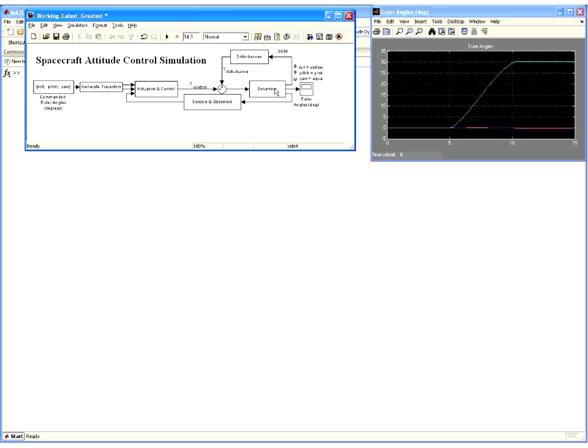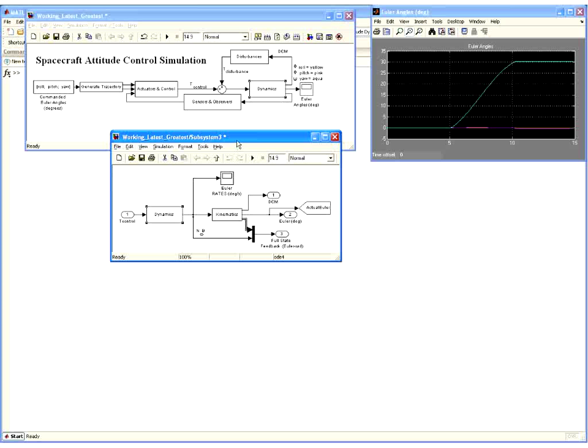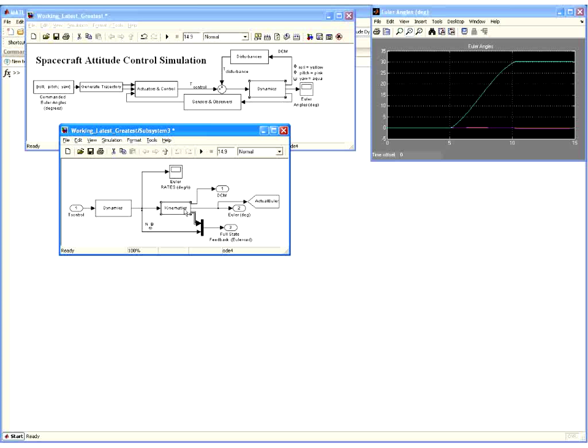Our direction cosine matrix references the position of the spacecraft's attitude relative to the orbit frame, and that is more relevant to figure out how much gravity gradient, how much solar and aerodynamic torques, and all of that, that we'll talk about next week. So in addition to just doing the dynamics inside this dynamics block, we're going to have a kinematics block where we calculate this direction cosine matrix. We're going to output the Euler angles just for display.